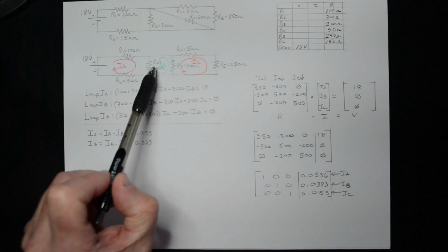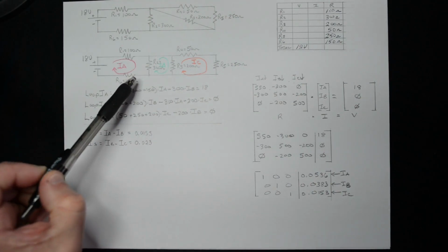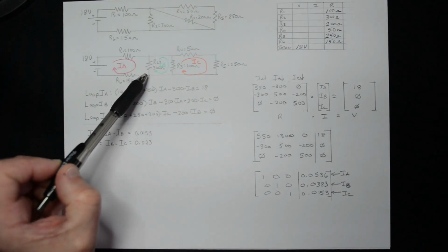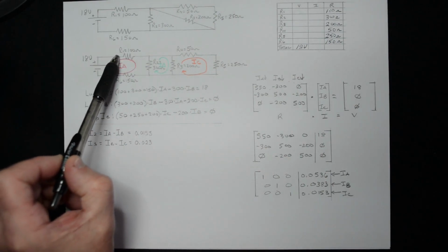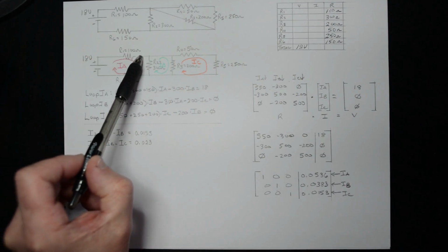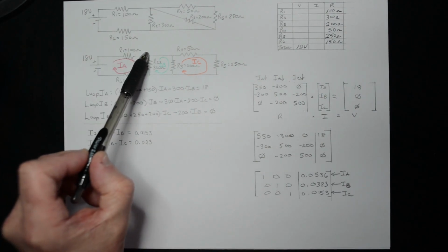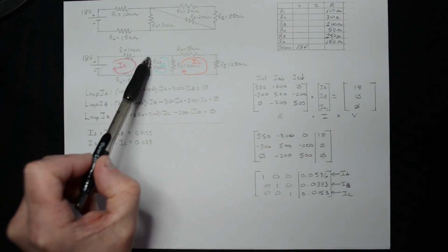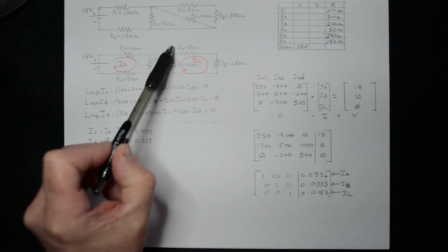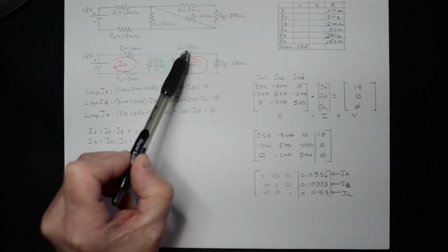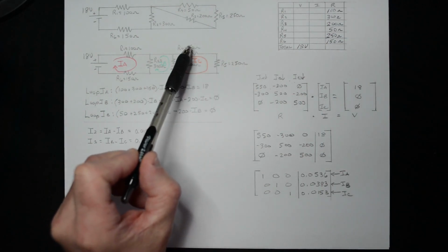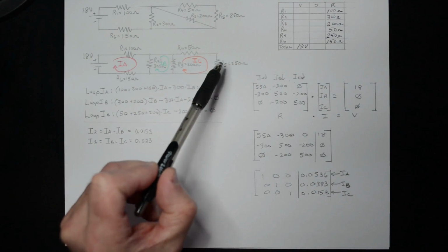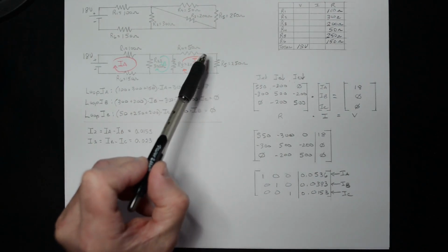And once you have the voltages here, and you already know the currents, you have a current going through here, you use Kirchhoff's current law. So the total current, which is also I1, also ends up being I6, this amount of current minus I2, which you can calculate, minus I3, which you can calculate, will give you the current in this branch. And once you have the current in this branch and you have the resistances, you can then calculate the voltages, V4 and V5.